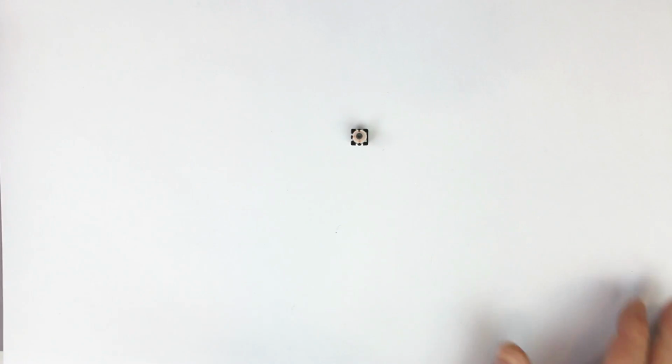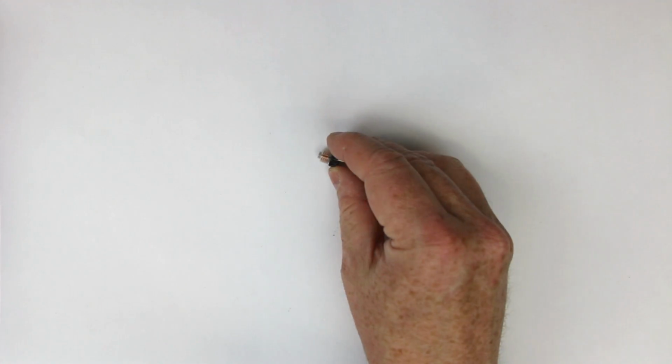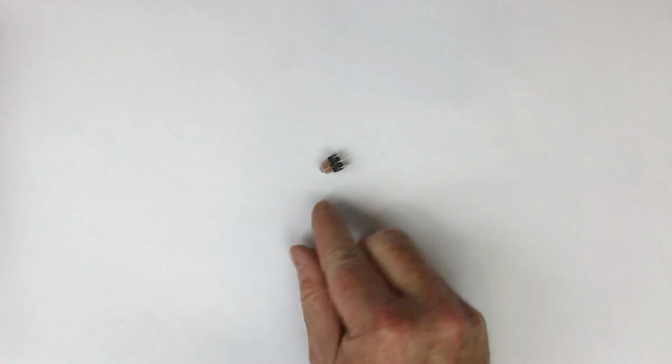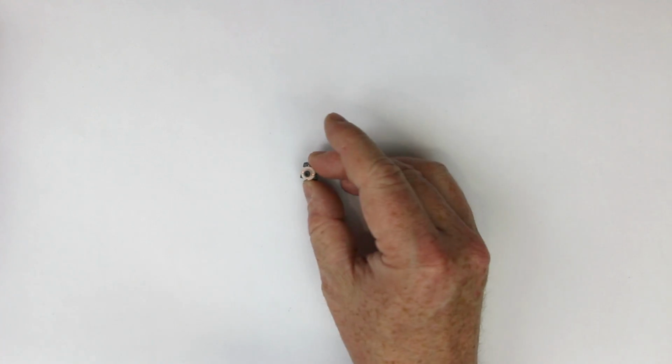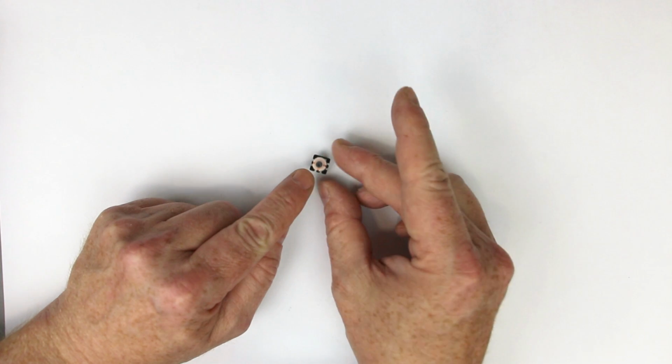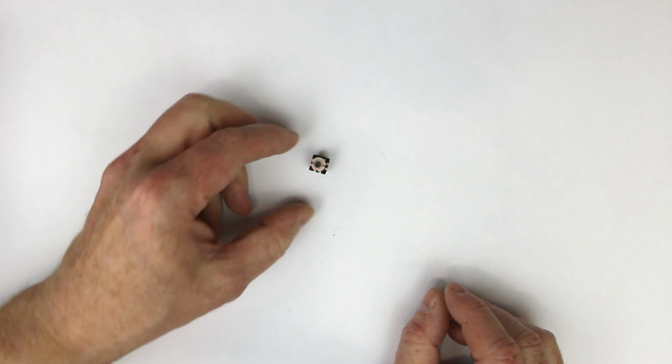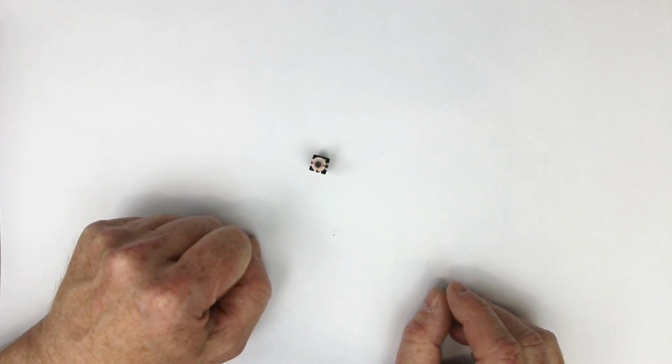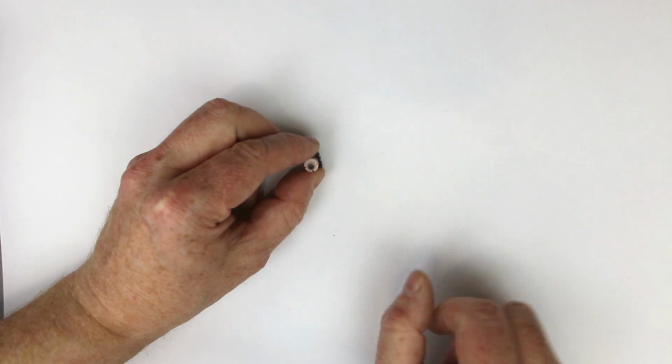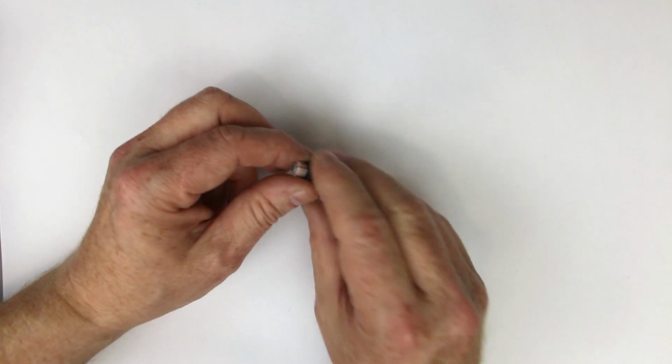But even this little piece here is a magnetic antenna. If you look closely, you can see there's a coil, and there's even a kind of miniature ferrite rod in the middle, and by turning it you can tune it. We'll also discuss this later.